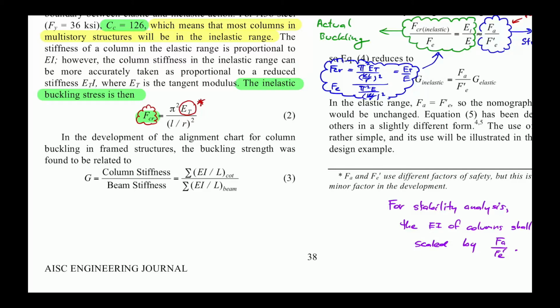So that causes the problem that you do not get the buckling column curve that looks like this one. If you have the cross section without the residual stress, you get the blue line, but the reality is that your residual stress just causes this transition.